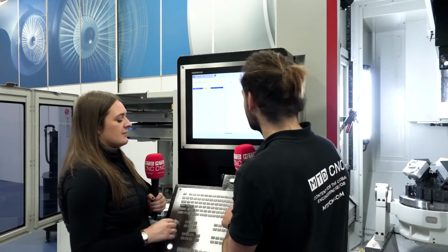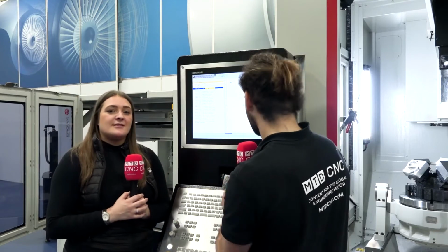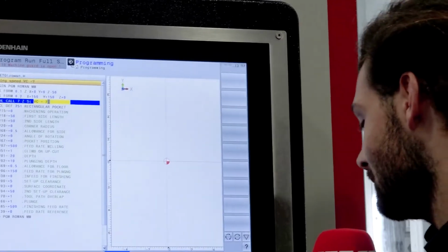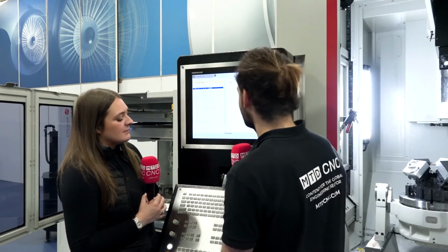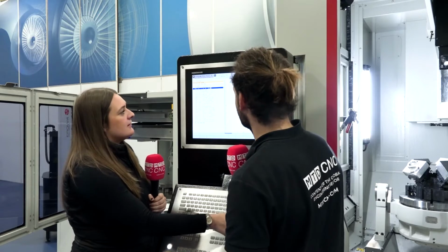Yeah, so actually, if I go, look at this, cutting speed. Let's say in aluminium, I guess 220 should be all right, depending on whatever the cutting tool manufacturer says. If we hit enter, okay, that's it. Yep, so we need a feed rate in there.